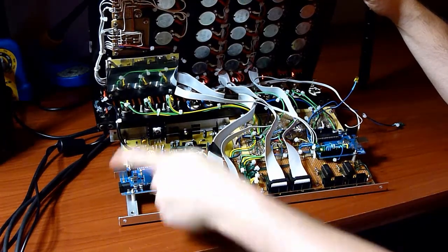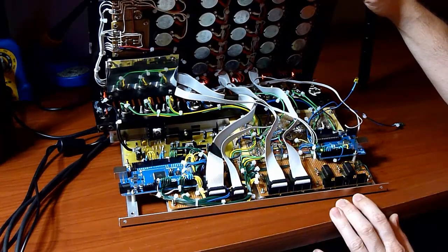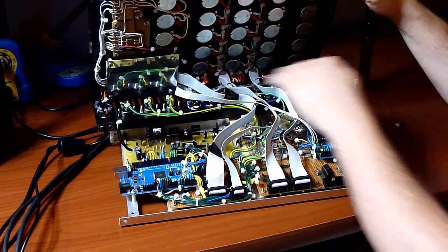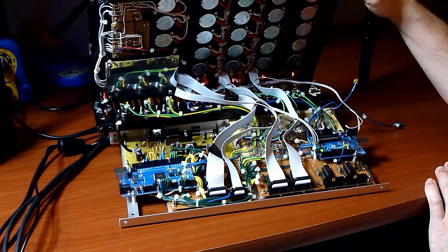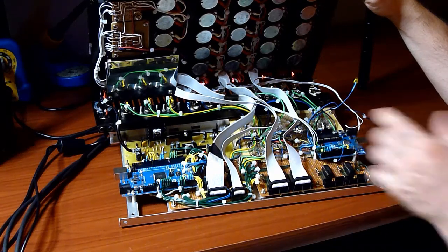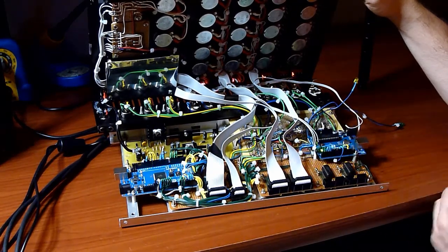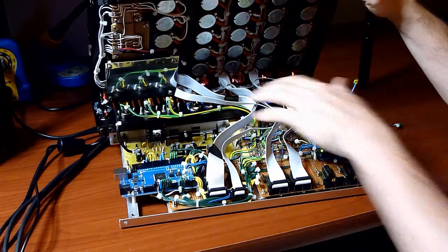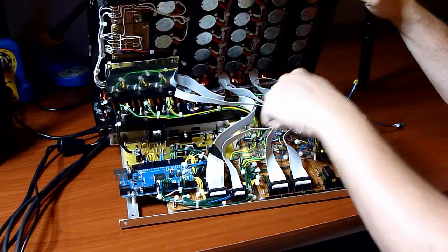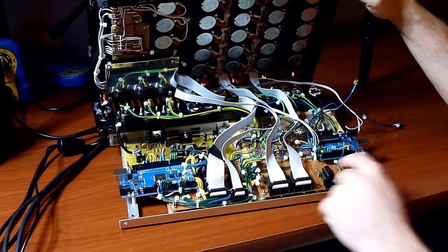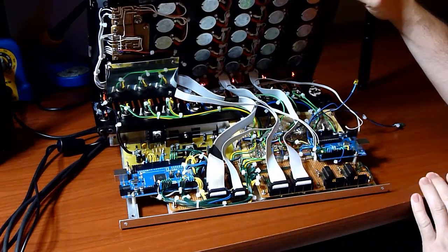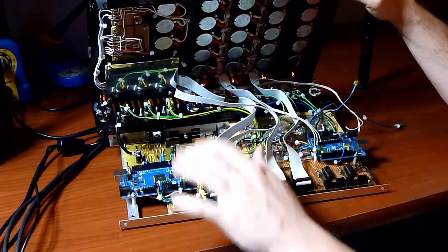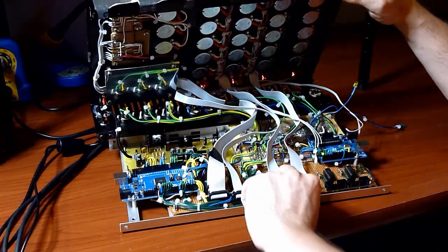Then we have the user interface controller here, it's an Arduino Mega, and it drives the screen and all the knobs here. Then we have the second Arduino here, which generates the signals digitally, and we have the digital to analog conversion stage, which is in this area here. And that part here at the bottom is for multiplexing the knobs, to have lots of knobs with just a few inputs on the board.